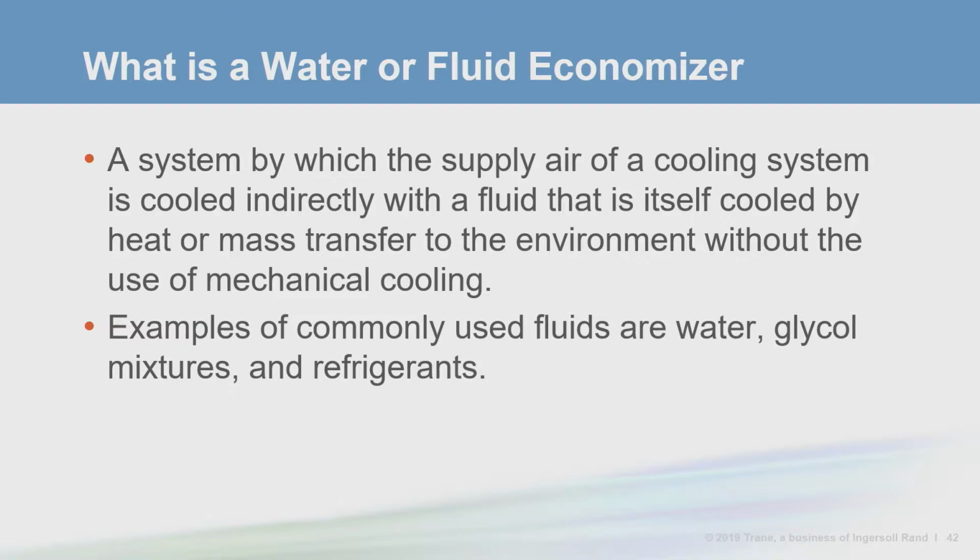In water-cooled systems, this often looks like a heat exchanger with cooling tower water on one side and system return water or return air on the other side. In an air-cooled chiller, it's likely a fluid cooler in series with the chiller or water coils nested within the condenser coils. So what else does 90.1 say about their design?